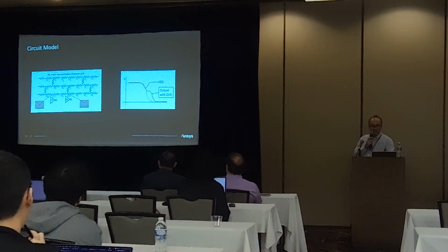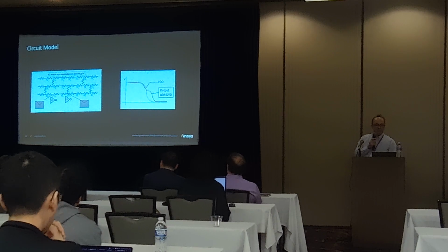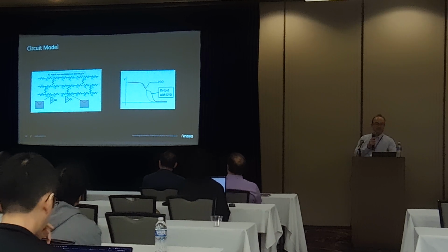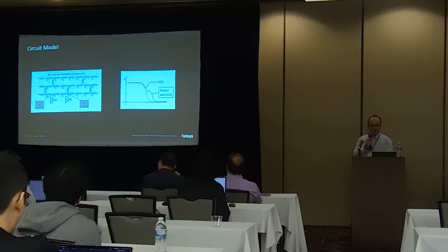So the electrical model is kind of simple. We have a very big RC mesh, sometimes L for the high level. But if, for example, your left side is victim and right side is aggressor, the victim is switching and the aggressor is switching at the same time. It may create a drop on the VDD rail, which will affect its timing. So that's kind of the model that we have. Take into account that we have big RC meshes, or resistive meshes to simplify.